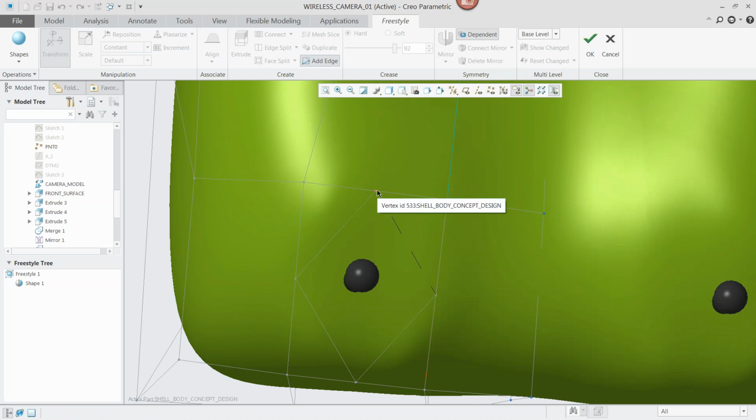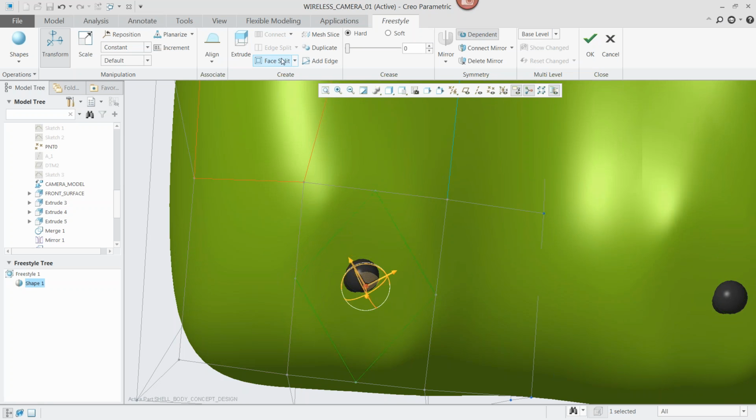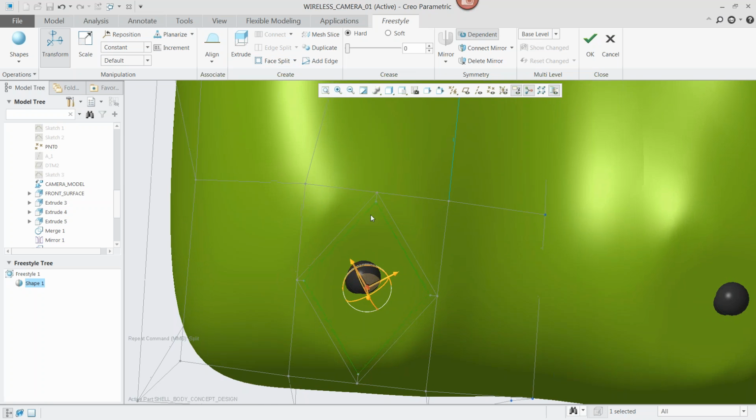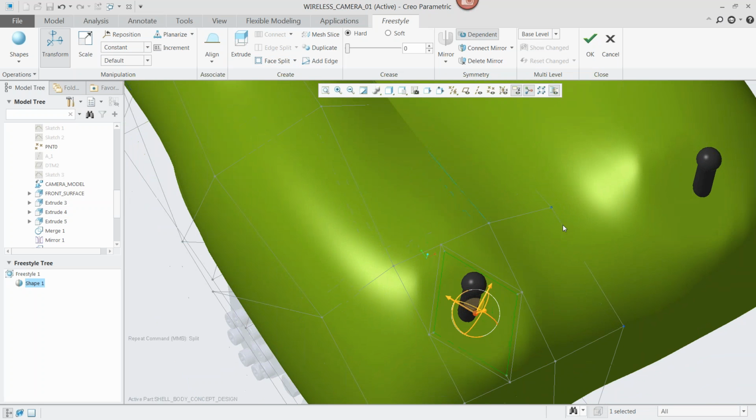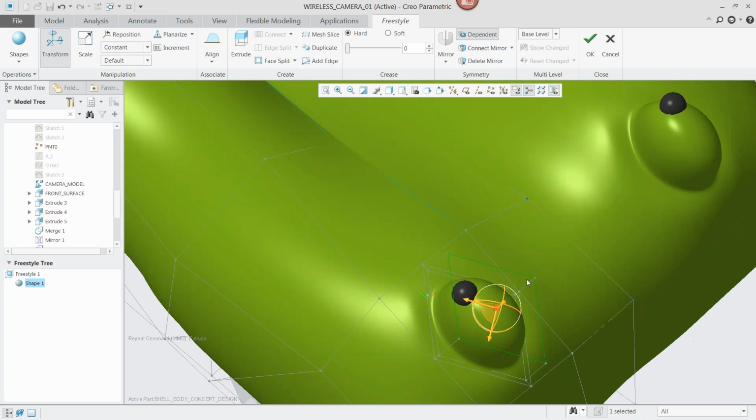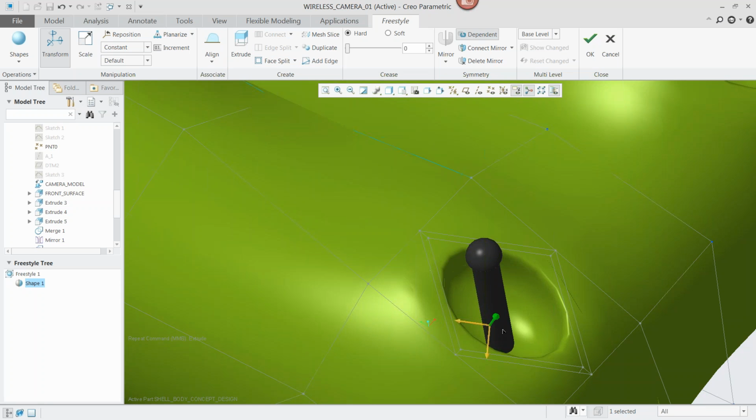And I can utilize this to have separate shapes within Freestyle, because that's the idea of Freestyle, right? To be able to model these very quickly into different shapes, different orientations. I can also do some face splits, so anything from 10% to 90%, basically doing an offset of what I see here. And so I have these antennas sticking out because I imported that mesh, but it's not really facilitating for these antennas. So let's fix that up. Let's do an extrude. And we're going to create these mounds, maybe some dimples or something like that, so it makes it look a bit more pleasing.